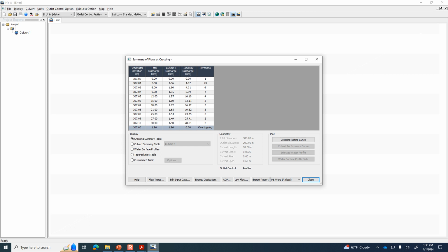I see some people shaking their head no. Absolutely not. To get 25 cubic meters per second through this area, only 1.5 is going through the culvert, and 23.45 cubic meters per second is going over the road. So this culvert is wildly undersized. It's much, much too small if we're truly trying to get 25 cubic meters per second through there.